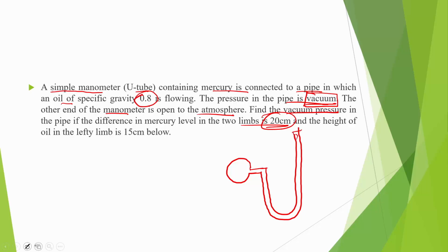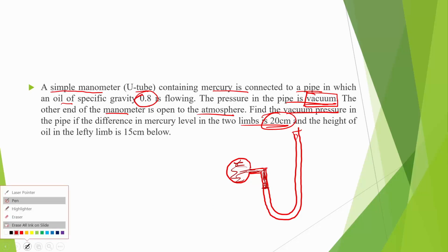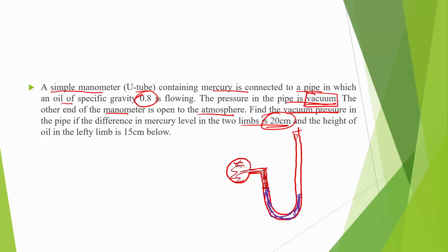since it is vacuum pressure, the level will be like this. So we have the metered fluid here whose pressure we are measuring, and there will be the manometric fluid, which will be again here. It will be up to a certain level here. Since the pressure here is vacuum, the fluid will be trying to enter into this system, so the level will be below the pressure here. So this is our reference level AA. This is your H2, this is H1, and this is your pressure PB.